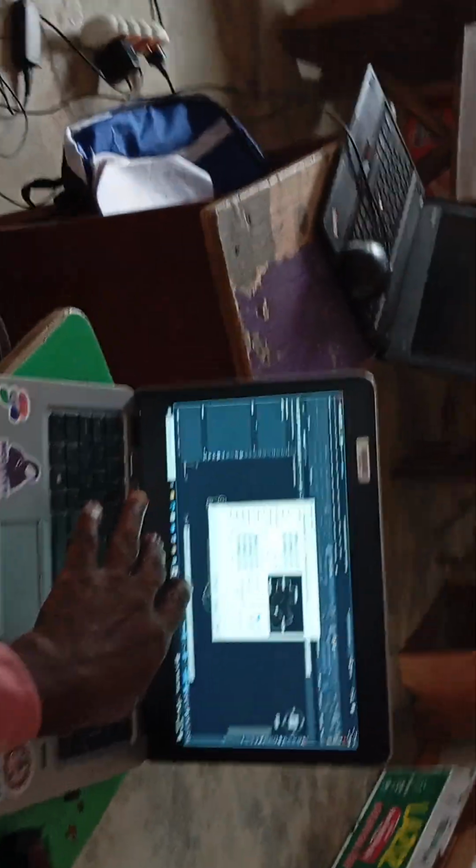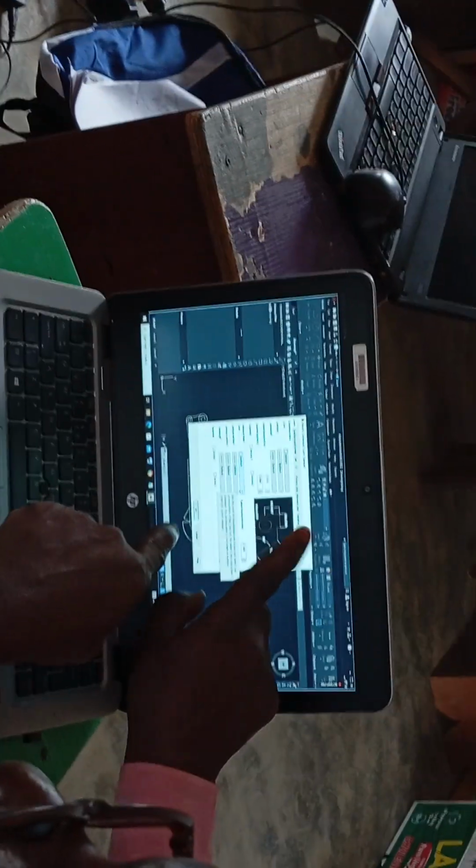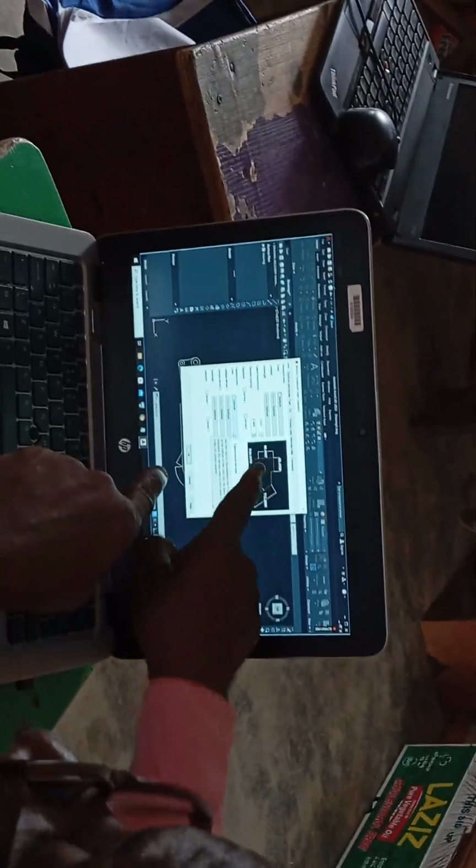So you check on the offset from origin. That's how close your dimension line or your extension line is to the main drawing. Main drawing is this down. Let's put where, what did you put, the 10, right?